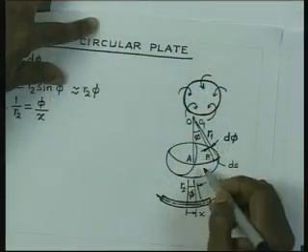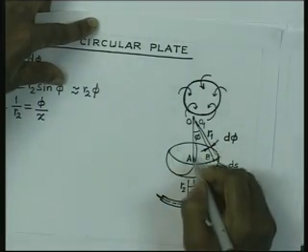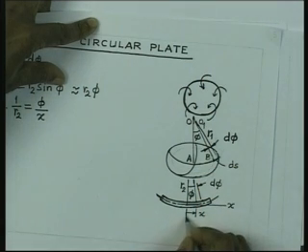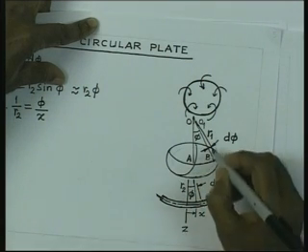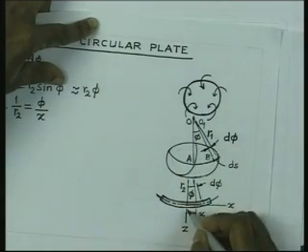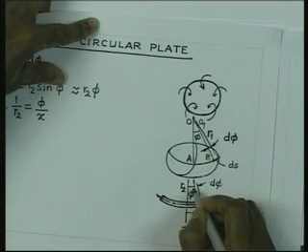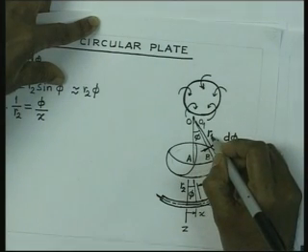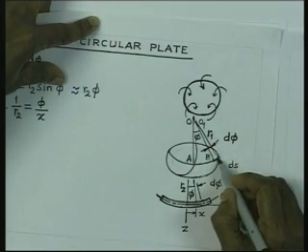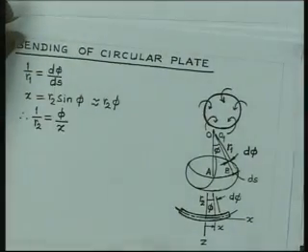Before I do that, I would like you to again get back to this sketch here. In this sketch, we have shown that this is the curvature in the plane. If you consider that this is z direction, so in the xz plane, we are considering the curvature to be r1, and this is y direction. So, therefore, in the yz plane, the curvature is r2. So, this is the curvature r2 which is phi by x, and this curvature r1 is nothing but, if this portion is ds and this angle is d phi, then d phi ds. So, we have already got those.